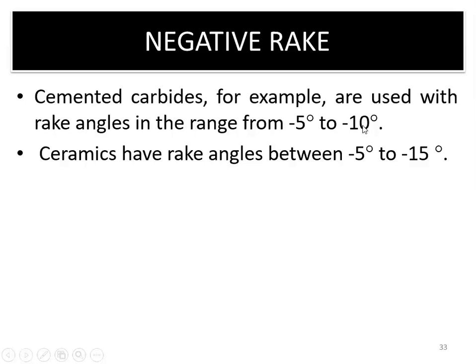Because the more angle you give, the more the machining cost for manufacturing the cutting tool will increase. So the best way would be no angle at all, but that can't be because we need sharp cutting edges. Therefore a particular geometry we have to give. That depends upon the application or requirement on the machined surface quality, the value of the rake angle we are going to give.